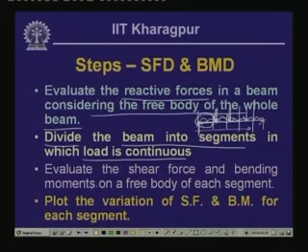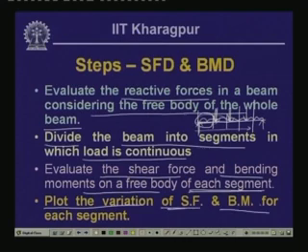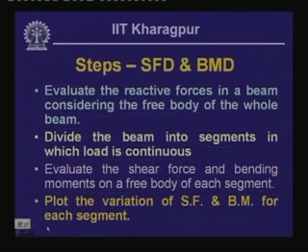So, this is what is mentioned over here, that evaluate the shear force and bending moment on the free body of each segment, and plot the variation of shear force and bending moment for each of such segments. Once you do that, then you will get the shear force diagram and the bending moment diagram of that particular beam. So, these are the steps one has to go through to draw the shear force and bending moment diagram.